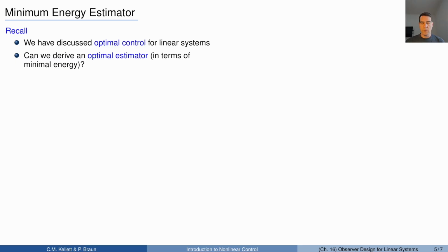So this was one example of an observer design, and you should have understood now the concept of an observer, namely recovering the information contained in the state X just based on output measurements Y. And then in this case the Lüneberger observer is a simple observer for linear systems, which can be used using similar concepts as a linear controller by designing an output injection term L instead of a controller matrix K.